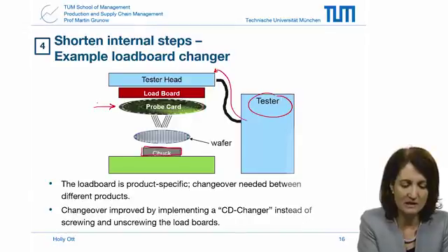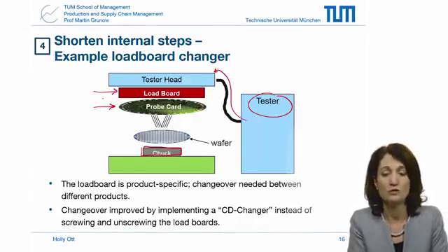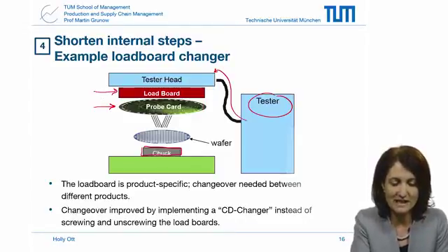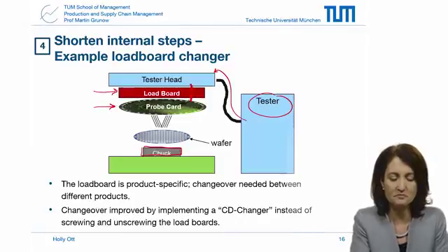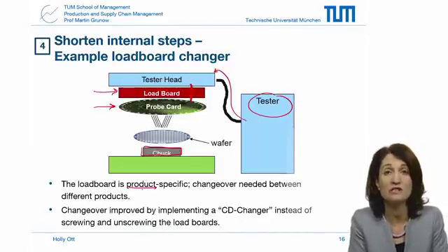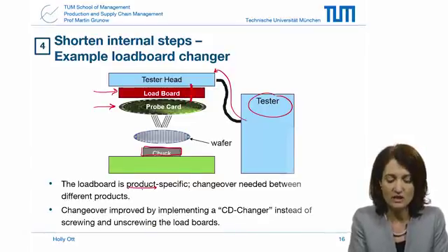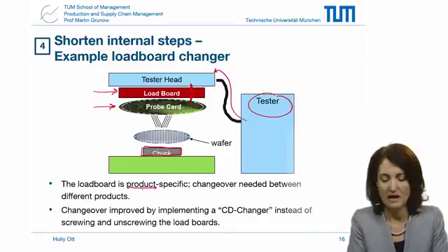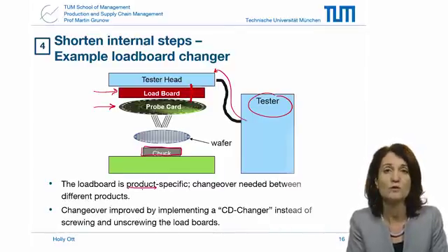Now, in some cases, you also need a so-called load board, which acts as an interface between the test head and the probe card. And the load board as well is product specific. Every time there's a change in product, you need a changeover for that load board and for the probe card.